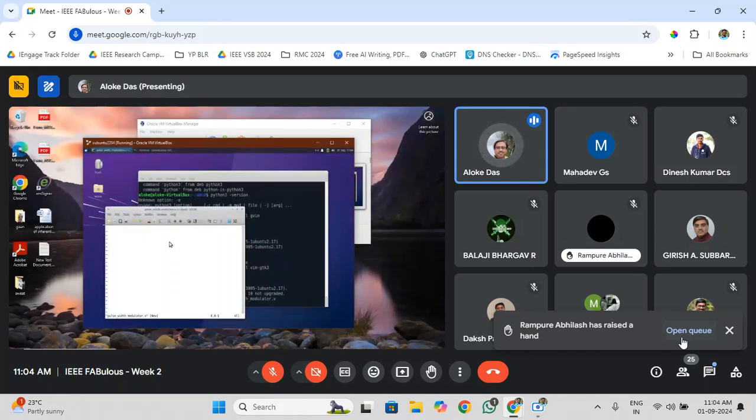There is something called insert mode, non-insert mode, like that. If you press i on the keyboard, it will go to insert mode. See, INSERT is at the bottom, and you can start writing your design. Module pwm, okay, like this. Escape, then :wq, write and quit.